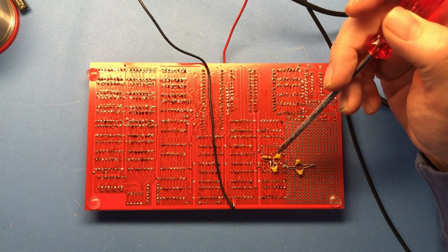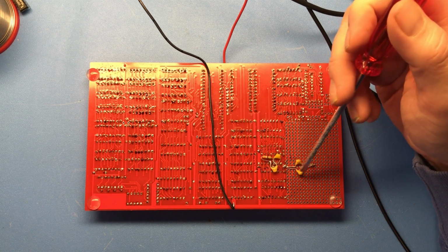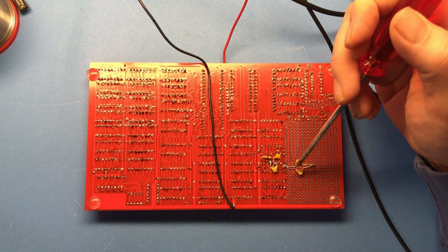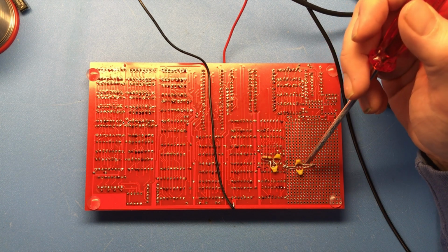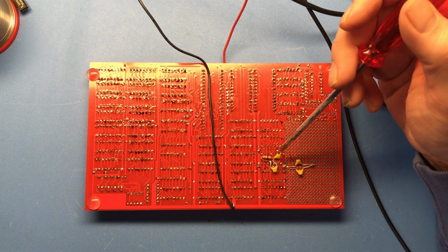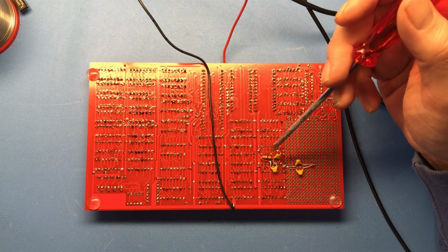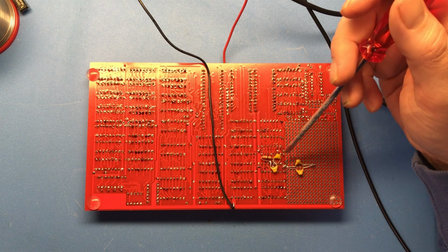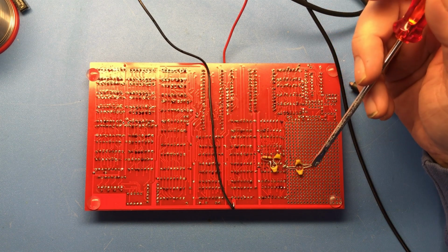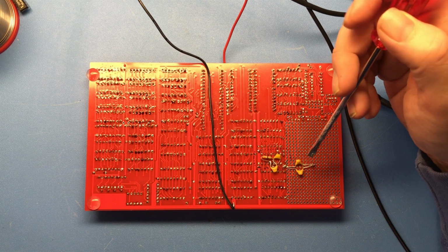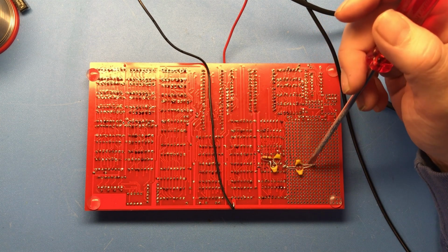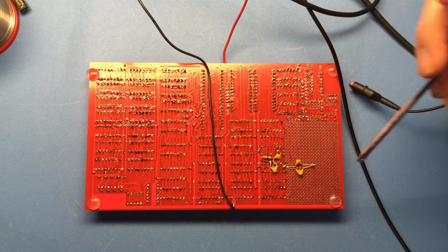And this is the whole mod that is done to this board regarding the oscillator. I do have some concerns about this, because I don't have any way of measuring this accurately enough. If there are some small variations in this frequency, I will not be able to do a proper measurement with the scope, because these fluctuations are very difficult to observe with the scope. But the clock is ticking on the frequency we want, mostly at least. So this will be it for now for the modification of the oscillator circuit.